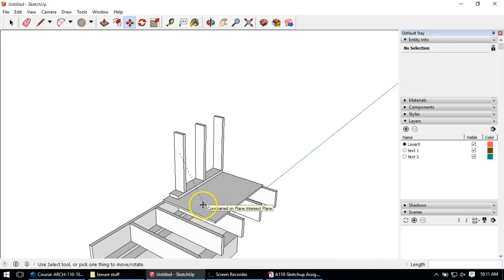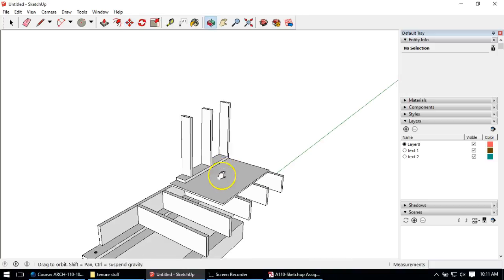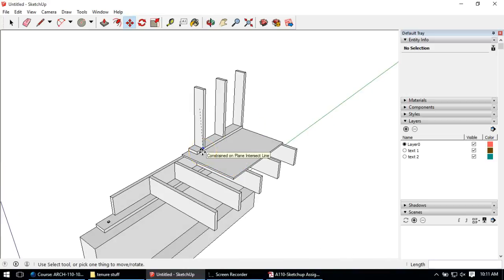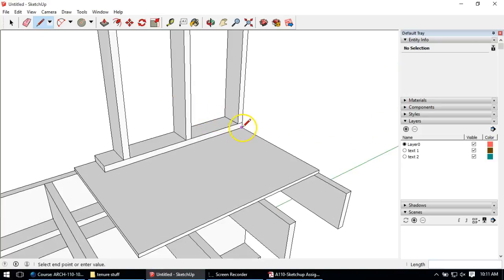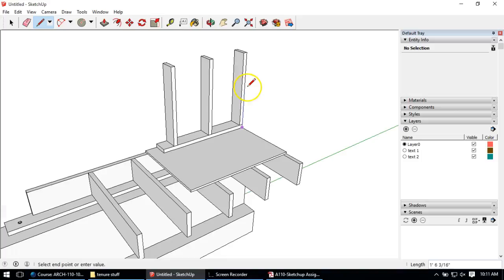I'm going to do the inside of the wall first, because the first drawing in the set looks at the inside, so we'll have to flip to the other page to see what's going on the outside. But note number 9 is the drywall, I assume, and it's 1/2 inch drywall. So I'm going to draw again, because there's no dimensions given, so I'm just going to use my pencil tool, click on the corner, sort of come up about halfway, 3/4 of the way through that stud, and then I'm going to come over, see the green line, and come to about midway between those two studs, then come all the way down. Actually, what I should have done, I'm going to undo that, I'm sorry. I'm going to undo that line.